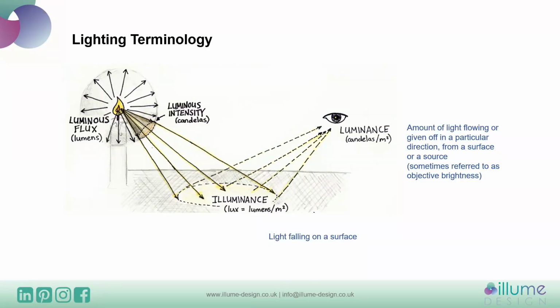It's very visible from the hedgerow and looks like a very bright source because it's directed in all directions and you can see that lamp and it looks very bright. But actually, when I measure illuminance at that point, I may get 0 or close to 0 because of the aspect of this being two different things. The light falling onto that surface at that point is actually quite dark, but you can see the lit source